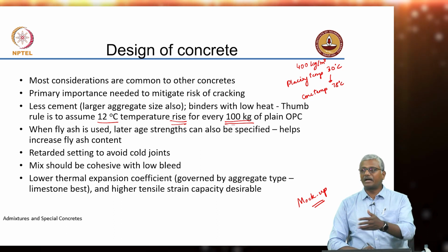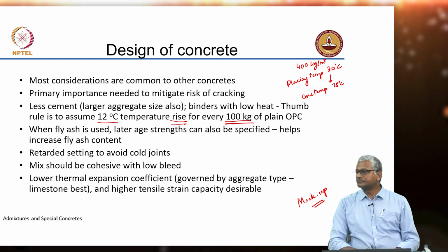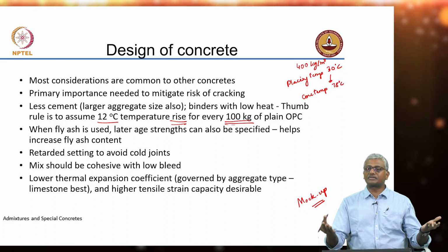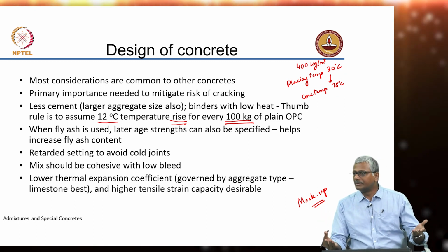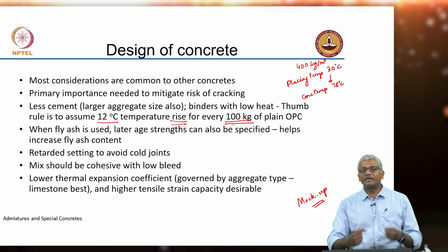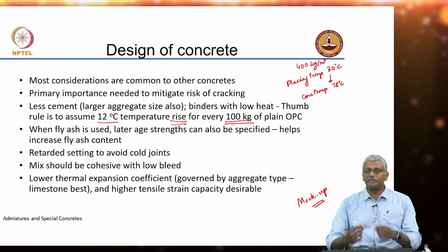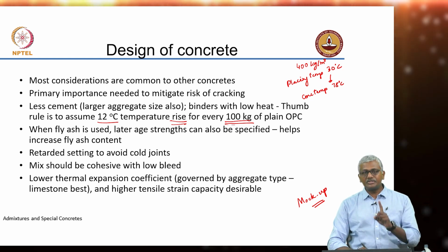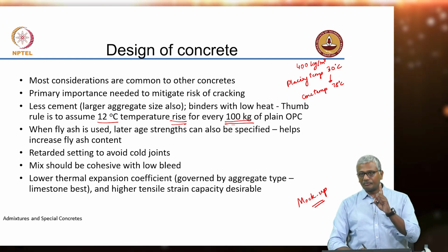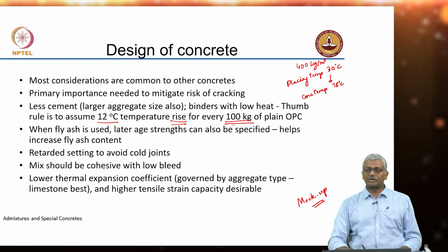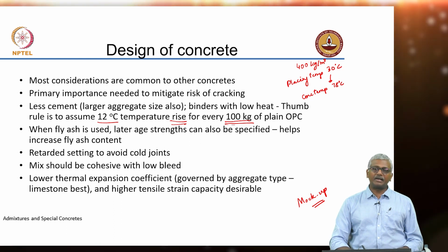Less cement, perhaps a little more water. More water means the rising of temperature of this concrete is going to be more difficult, because more water means more heat absorption will take place. Less cement means less heat development will take place. So in general, when designing structural members that are likely to be mass concrete, it's best to go with as low a grade as possible.